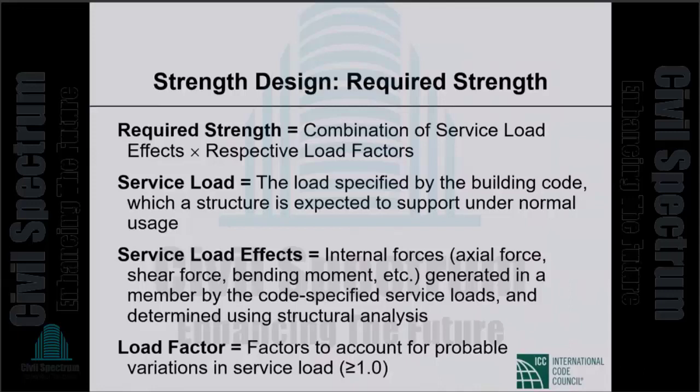What is required strength? So there are service loads. Let's start there. Service loads are the loads specified by the building code which a structure is expected to support under normal usage. Okay? There are service loads and then there are abnormal loads. We are talking about service loads specified by the building code which a structure is expected to support under normal usage. So service loads, so many pounds per square foot of live load, that would be a service load.